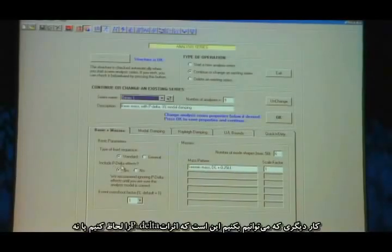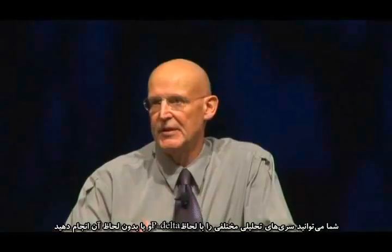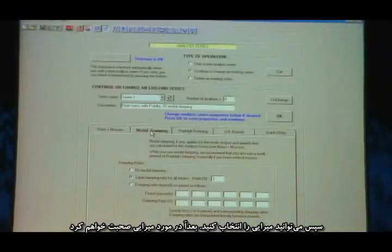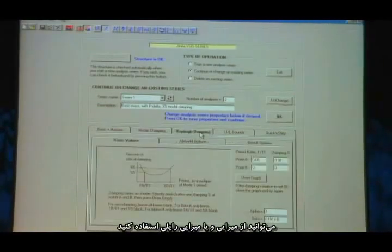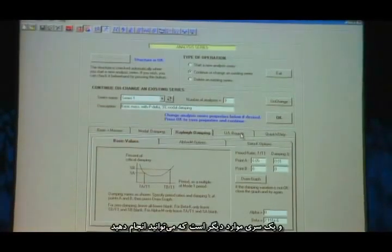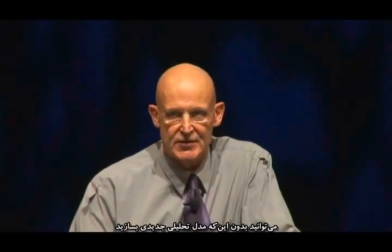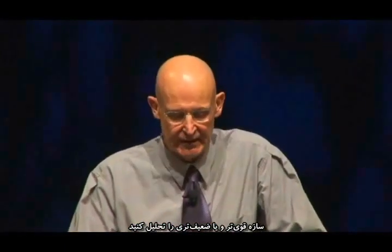The other thing I can do is choose whether or not to use p-delta effects. So you might run one analysis series ignoring p-delta effects, another one including them. And then you can also vary the damping. Later on today I'll talk about damping. You can have modal damping or Rayleigh damping. And there's a bunch of other things you can do. You can actually even vary the strength of the components using upper and lower bounds if you wish. So you could analyze one structure which is rather weaker and another structure which is rather stronger without creating a complete new analysis model.